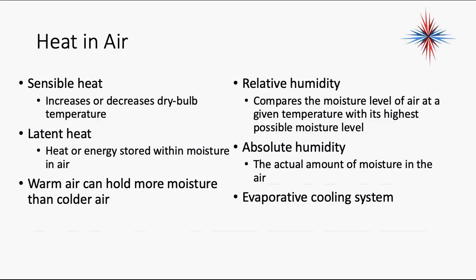So we have different heat in air. This comes down to enthalpy. Again, think about your psychrometric chart. Enthalpy contains sensible heat and latent heat. Sensible heat I can measure. Latent heat I can't measure, but it's heat or energy stored within moisture and air. Warm air can hold more moisture than cold air because of dew points. Eventually, cold air will get cold enough where the moisture just falls out of it in rain or condensation.